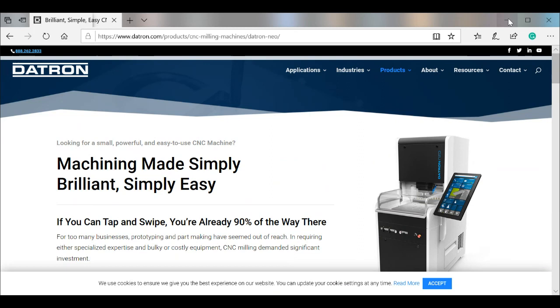Okay, from Chema also we have another interesting question. Have you got any experience using the cutter plotter to fabricate handmade photolithography masks? Yes. Okay, and he said, you said the resolution would be 100 micrometers, so this sounds like a good option for fabricating cheap photolithography masks. Well, it's not so much the resolution, but the tolerance that you get. In fact, with the cutter plotter, you can make structures down to maybe 250 microns.